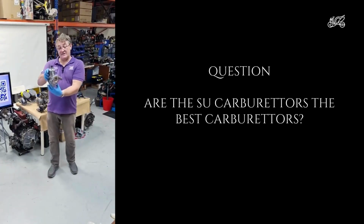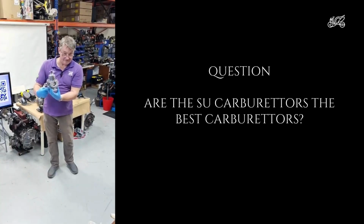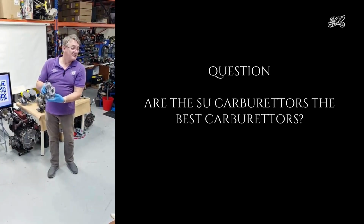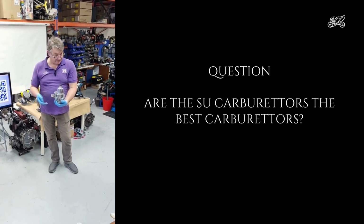Well, okay, and they attempted to fix it with this. So this is all still an SU, but this is what they call HIF, integrated float chamber. So the float chamber, instead of hanging on the side, is now integrated underneath. Yeah. So they got more complicated with time as they tried to keep up with, especially emissions. Right, it got more and more difficult to meet emission standards.